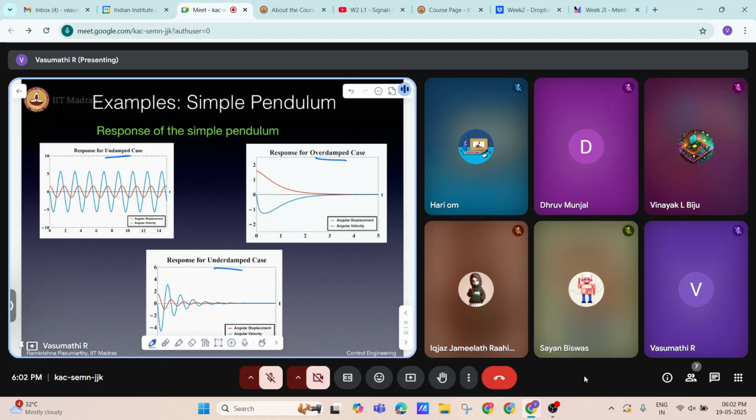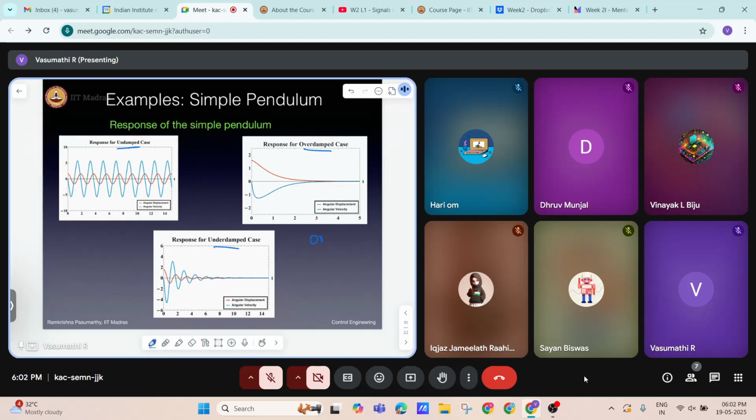Okay. As most of you gave inverted thumbs up, we will see what under-damped systems are. Generally, we say there are different orders of the system. The order will be equal to how many energy storing elements are present in that system. Energy storing element, okay? Not energy elements, it's the energy storing element.